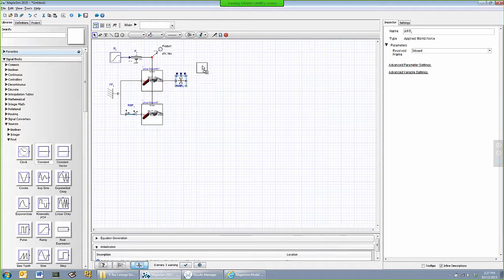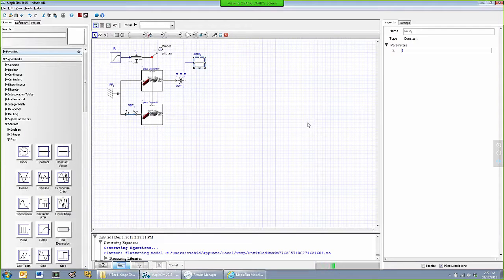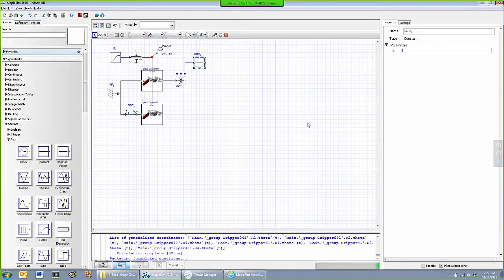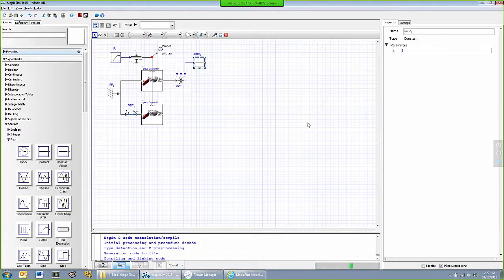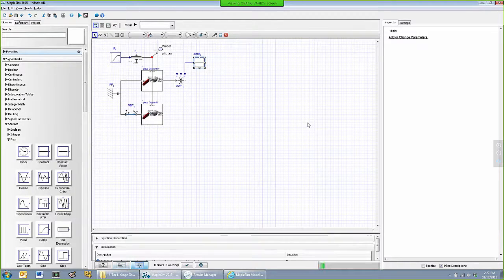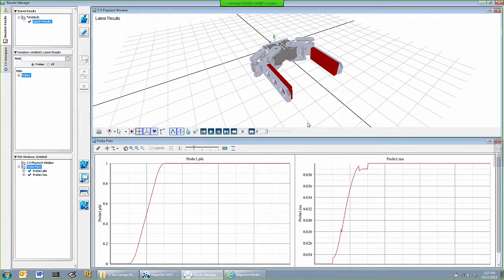The reason is that I'm going to continue this model and do a little bit more exploring of the effect that we are beginning to observe, a combination of the external force effect on the model together with the internal reaction or the inertial forces. So I added a global force to one of the fingers in the x-axis with a value of 1 newton, and now I'll see an interesting result in the torque and in the displacement.